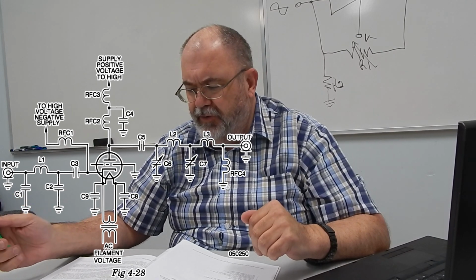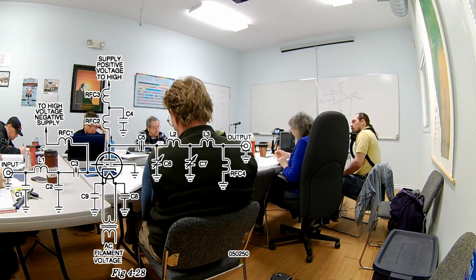What is RFC1 doing there? What's its function? It should block any RF going back to the power supply. Precisely, yep. Just remember that a power supply is as good as a ground to RF.